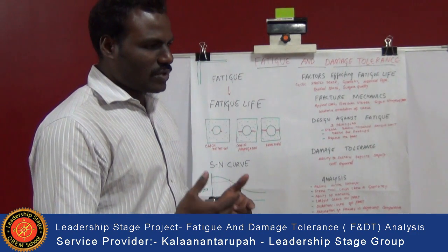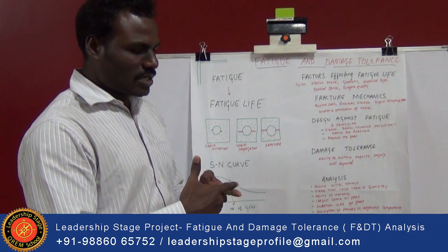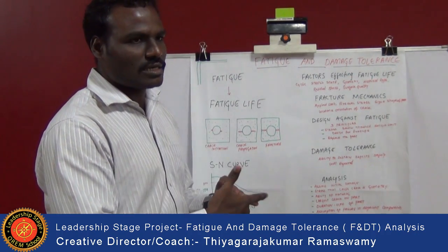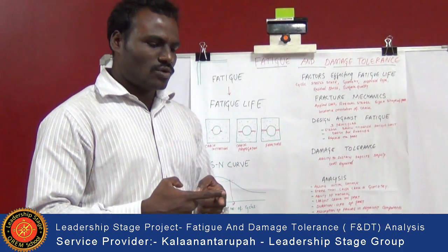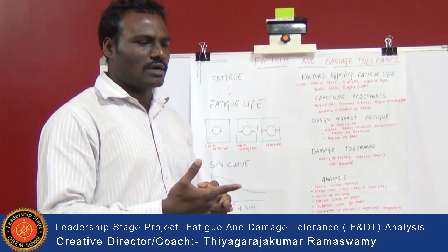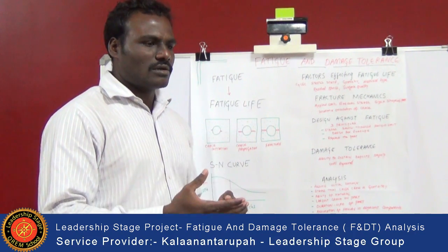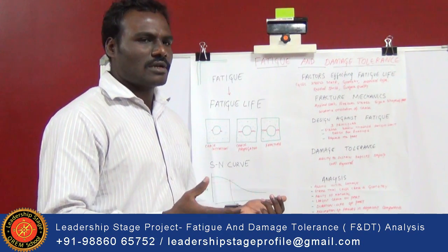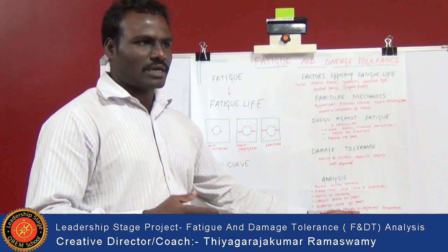It is nothing but, if a part is failing, the load applied over the part should not transfer the forces to the adjacent component or adjacent part, which leads to failure. So we need to design the component with adjacent ribs or adjacent frames which will not transfer this failure to the adjacent component, ribs or frame.